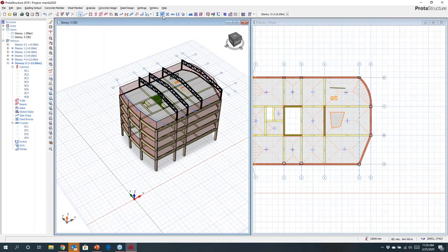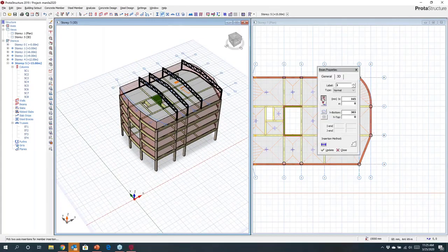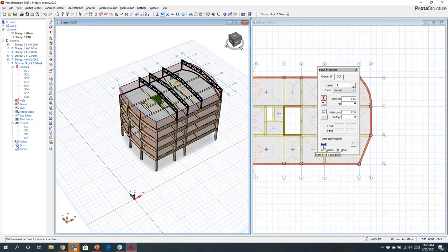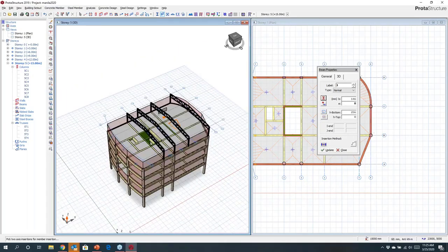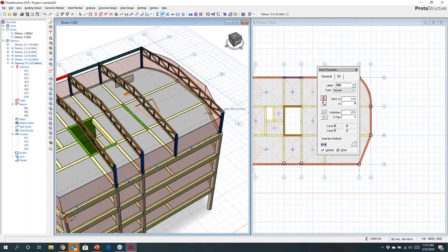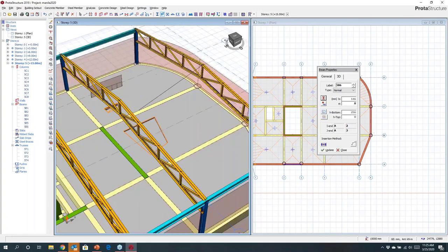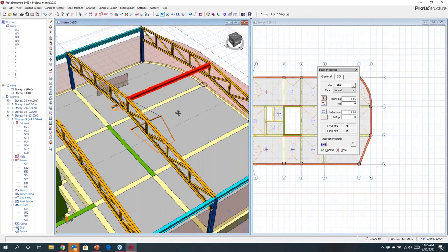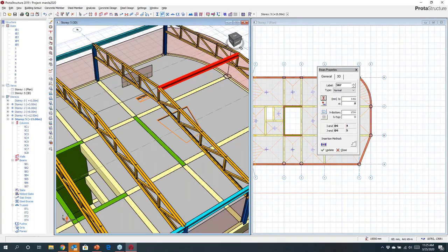Okay, I'm also going to, at this point, come in and create some beams. I'm going to use, maybe I'm using UB, and we can just grab a section to start with. Okay, you can play with properties like fixity. So if I want to just pin the end of the member, I can just come pin it, and I can just click each end, and we will automatically break the members to create those elements. Okay. Now, you might have noticed that we've got smart snap points, so you can model to different points very easily. I'm just going to model maybe the top.